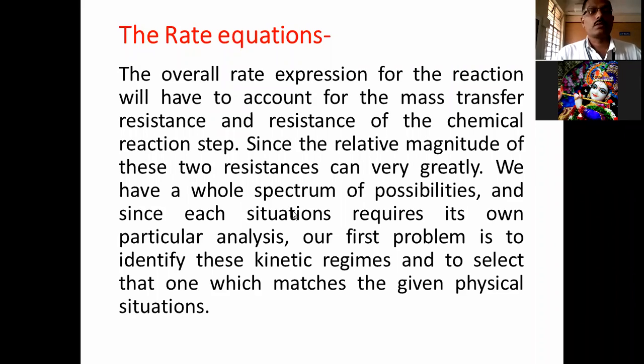So this is the very important mass transfer and chemical reaction rate. This is entered in a fluid reaction, and the overall rate expression is determined based on this. We determine the mass transfer rate and the chemical reaction rate, and whichever one is the slowest, that slowest rate will be the rate determining step.